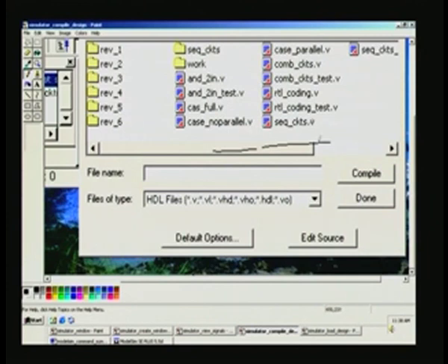Similarly, when everything is satisfactory as far as functionality is concerned, you will move on to the synthesis tool, wherein you do logic optimization as well as map it onto a target device, say a particular FPGA. So, at every step, you will be encountering plenty of errors to start with as a beginner, and we will have to fix them. After we take up synthesis, we will club both ModelSim and synthesis together and create deliberate errors, so that you can quickly learn and overcome them by practice.